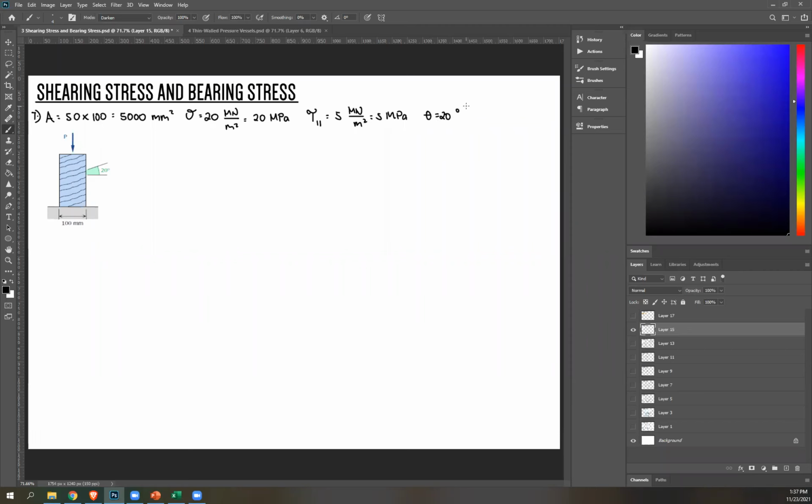So let's start. Now recall from our past lectures, the amount of stress given is usually also the same as the amount of equations that we need to work on. We're given two, compressive and shear. So let's work on both. Let's start with compressive. So compressive stress, again, that's just normal stress. And the equation for that is P over A. For compression, there's no problem. P would have the same value as your applied force P since they're both perpendicular to the cross-section of your wood. Okay, so I don't have to solve for P. Actually, that's what we're looking for.